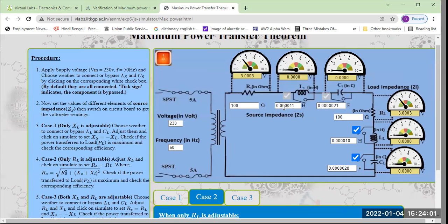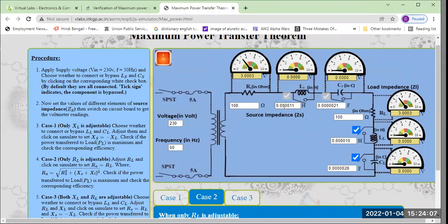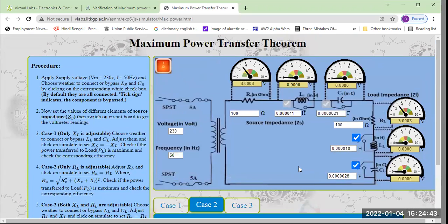so that maximum power will be transferred. Okay, if you add 8 boxes, then the load resistance or load impedance should be defined, because when I say box, that means a speaker. In this speaker, you can see there is a coil, there is some circuit where you can apply some capacitor, and ultimately it has some resistance. But what we actually need is that this RA should be equal to RL, so that your maximum power will be transferred. Otherwise you can see some speakers will not